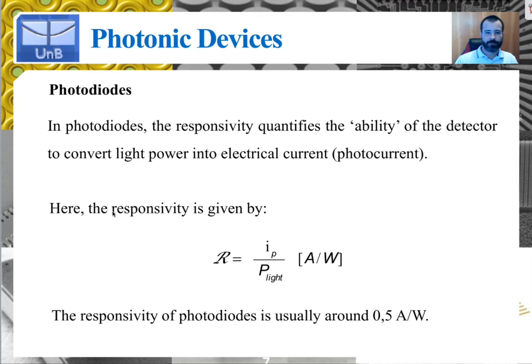And therefore, it only makes sense that the responsivity is going to be the photocurrent divided by the incident optical power. Okay, so again, if the device is sitting here and you have an incident optical power which is going to generate electron hole pairs which are going to be converted into a photocurrent, then you want an efficiency parameter which is going to give us the amount of photocurrent generated per unit optical power, in amps per watt.